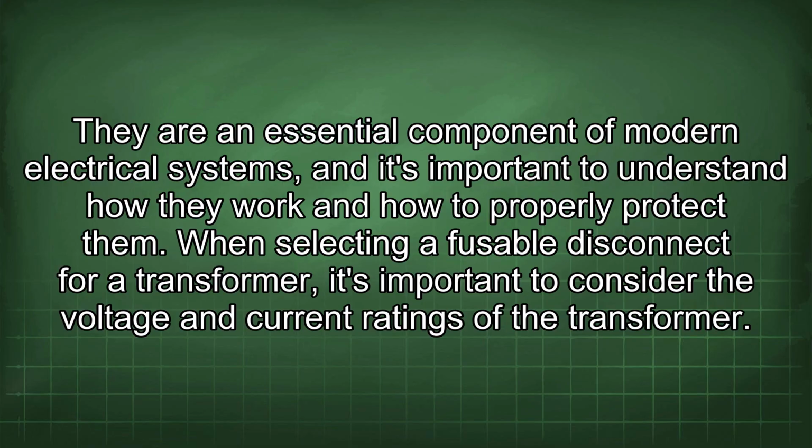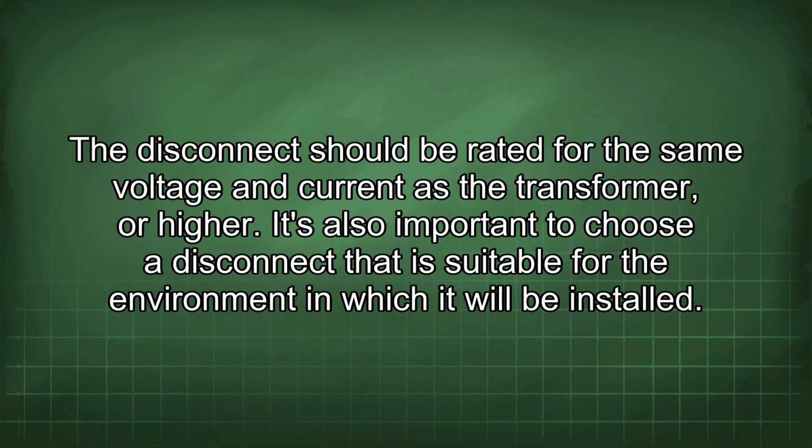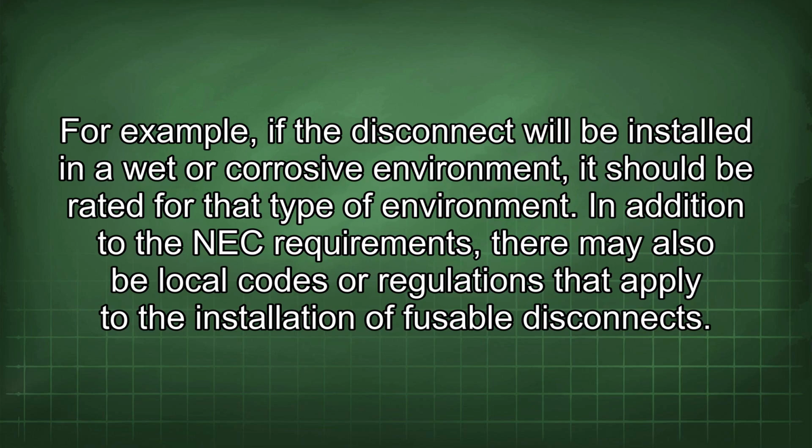to properly protect them. When selecting a fusible disconnect for a transformer, it's important to consider the voltage and current ratings of the transformer. The disconnect should be rated for the same voltage and current as the transformer, or higher. It's also important to choose a disconnect that is suitable for the environment in which it will be installed. For example, if the disconnect will be installed in a wet or corrosive environment, it should be rated for that